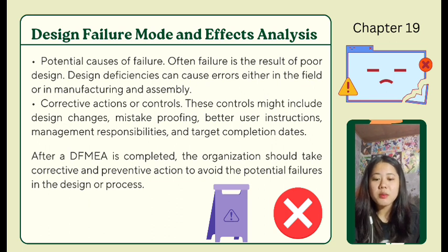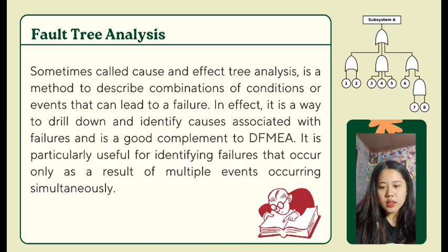So, after a DFMEA is completed, the organization should take corrective and preventive action to avoid the potential failures in the design or process. So, corrective actions appear in response to an error, while preventive actions may occur before one. So, fault tree analysis.